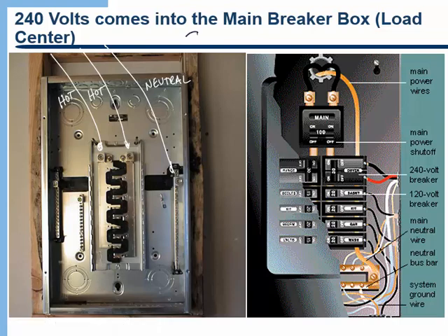What this first diagram shows you on the left is what is inside the breaker box. So that's what it looks like with all the breakers removed. It turns out that what actually comes into your house is 2 120 volt power lines. So 2 different hot lines and then a neutral line. And they connect to the back to what are called bus bars. So one side connects to this bus bar, one side connects to that bus bar, and then the neutral wire connects over here.